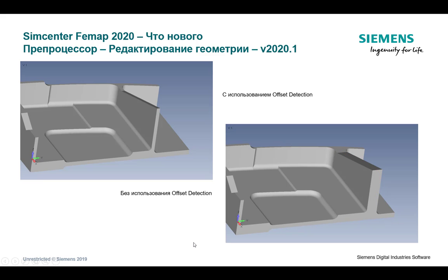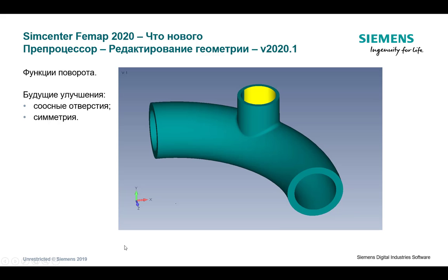Very similar to this, you can also rotate features around a vector. So essentially, if you just pick this one curve here, depending on what you have specified in your options, it's just going to know to grab additional surfaces that are going to move this whole feature. So what you can see is it's just going to move it over here and then move it again based on a specified angle and a rotation vector.